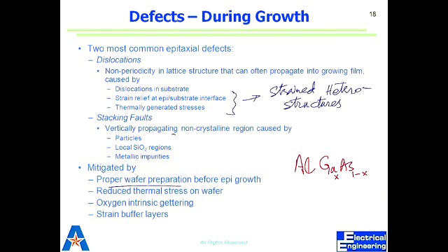And it can be a relief of that stress, which results in a dislocation and a void. Or this can be due to heat that is coming from the process that we do. It can be because they are stacked on each other, so that can travel along the vertical line, resulting in a crack type of defect. And they can be either because of impurities, particles, or silicon dioxide regions, because it's a high temperature process.